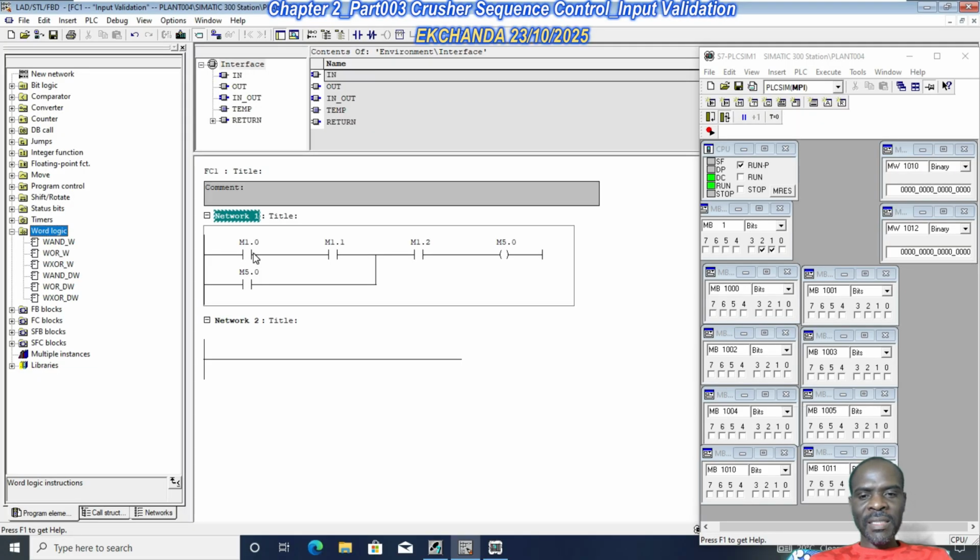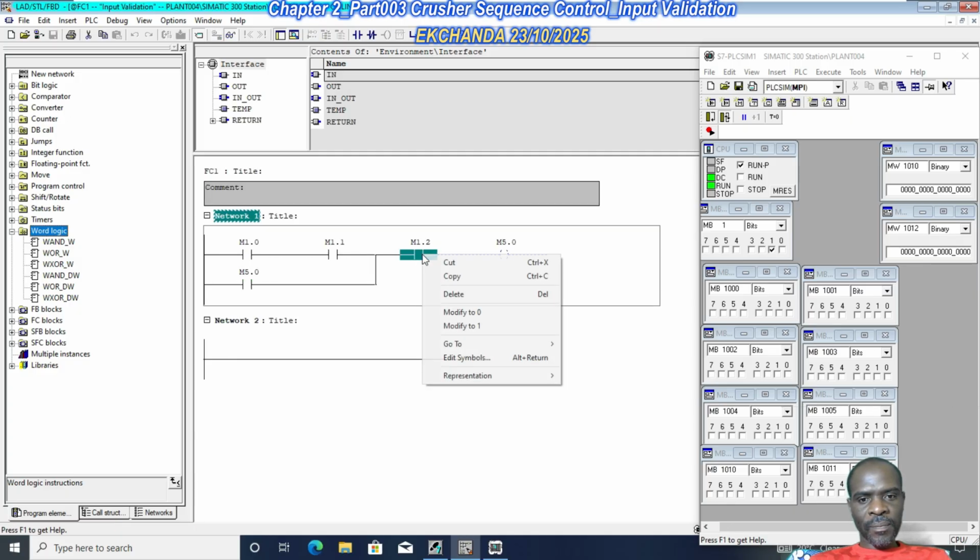But we need to monitor the condition of those inputs. All those protection inputs, we need to know when they're true and when they are false, and if for any reason they become false, we don't want the system to just self-reset. What our expectations are, it's going to be the following.